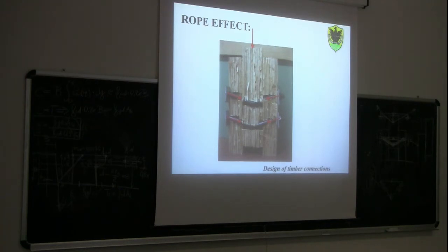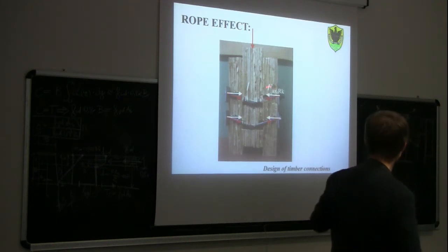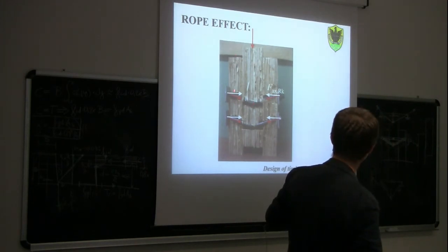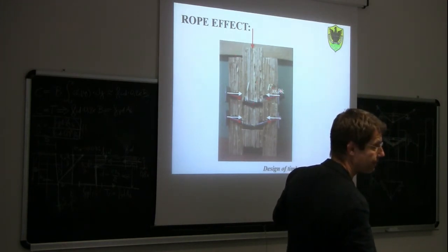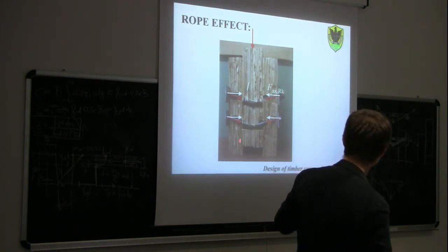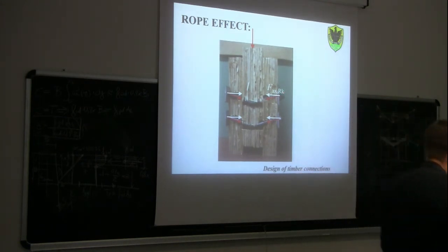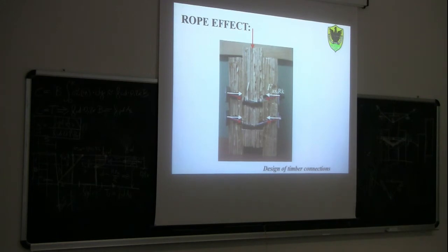This compression force, as you can see, will have a horizontal component. This horizontal component is going to compress this timber on this other timber here. But here, on the slipping surface, are the two surfaces free to slip? Well, if we apply a compression force, we always have a phenomenon called friction. We have friction at the interface between these two metals.